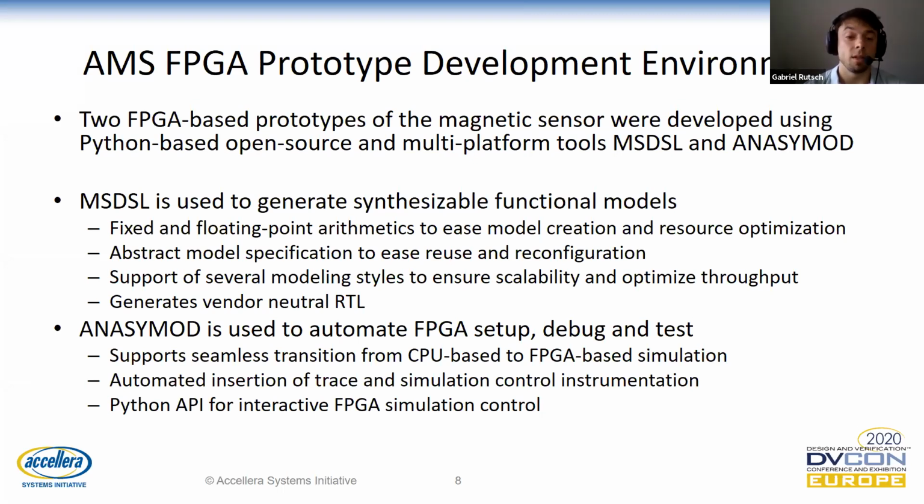In order to do that, there's a Python layer available that allows interactive control of the FPGA simulation itself. So what you could do, for example, is pause this simulation after a certain amount of time, then read and write signals in the design, and then continue the simulation.